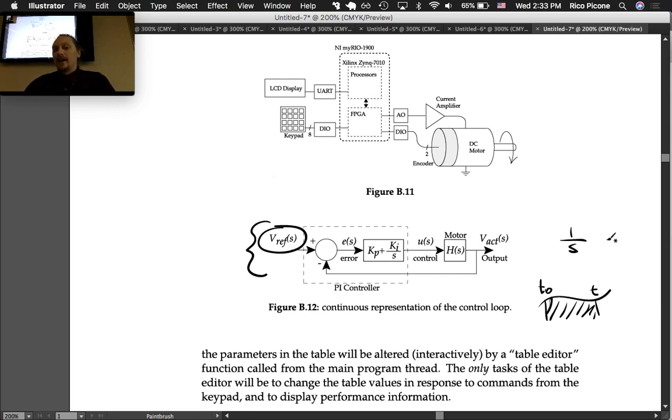This is really nice for fixing steady state error, because even if you have a small steady state error over a while, it accumulates and will give you a good response. This is a pretty safe type of controller. PI, there's not too much that can go wrong with it. When you add the D in there for PID control, it gets a little bit more dangerous. There's a lot more chance you're going to go unstable.